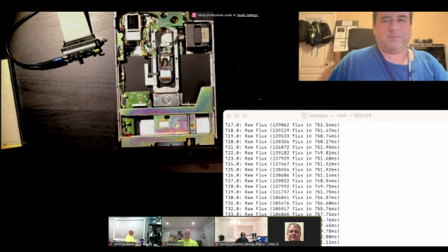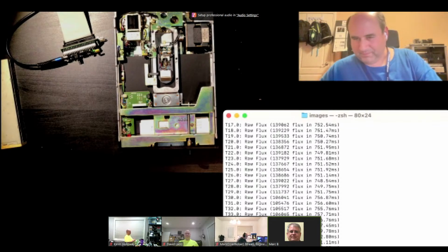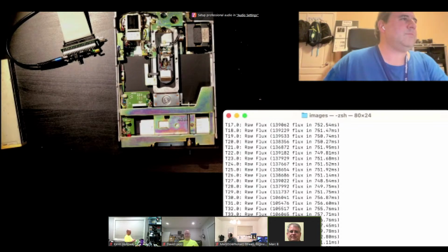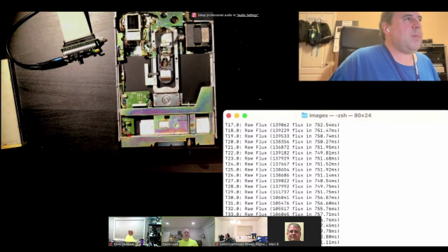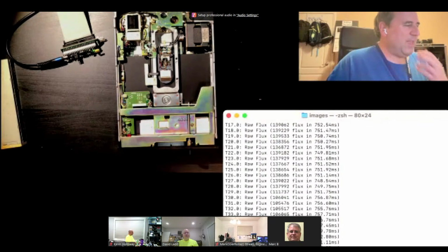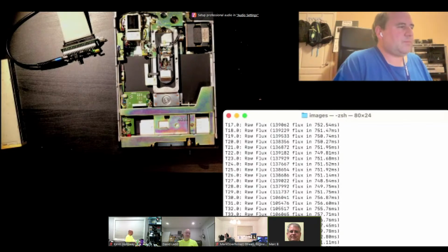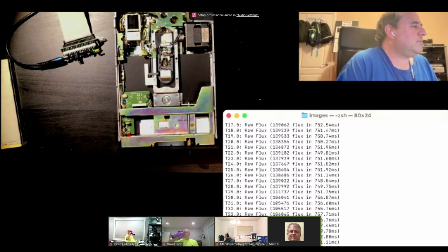So just for the audience, some drives, you can get an extra couple of tracks out of them before the head bangs against the hub. Not recommended, but sometimes you can squeeze an extra track or two out of them. On three and a half inch drives, I routinely got 82. There were a couple of drives I had that I could actually get up to 84, but that was a rarity. Those TEAC drives, with those 35 track TEAC drives, weren't happy with it.